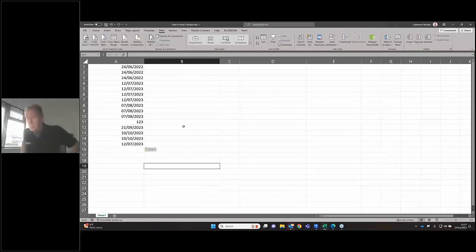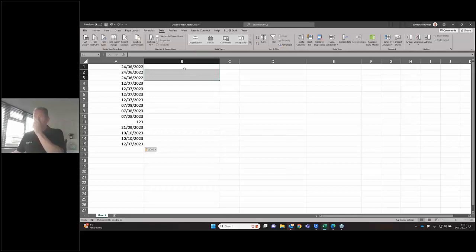and I can now see that data set. Now, in Excel, obviously you can set up data validation to highlight anything in red that isn't a proper date. But an even better workflow is I can have Excel flag up pass or fail in here based on a formula that I can write in here. I can then pass that data directly back into Revit and then pass that back to the consultant so they can see all of the data that they've got to go and repair or fix.